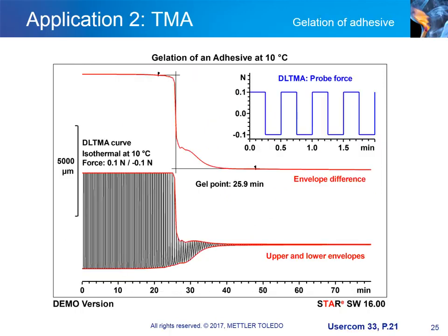An adhesive is shown initially in its liquid state. During isothermal cure, the viscosity of the adhesive increases as cure or cross-linking progresses. From a technical point of view, the so-called gel point or pot time is of major interest. It denotes the time at which the repositioning of parts in the evolved structure is no longer possible.